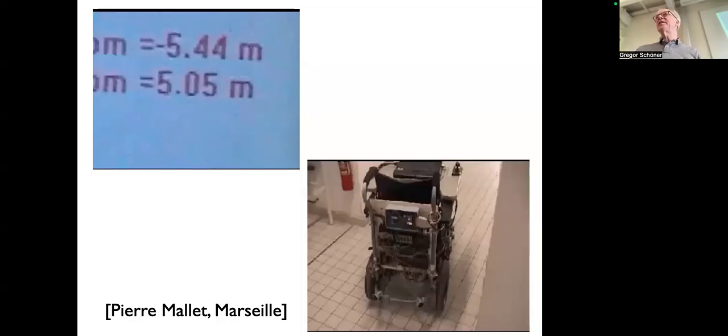In other cases, it is the sensors. The sensors need some time to set up this infrared. There's the flight time, but that's negligible. But they need to average a little bit. It's like heat, it's infrared, and the sensor has some time it needs to make a measurement, and you have to do that separately for every sensor because they interfere. And that gives you the minimum time for one time step. We get one reading from every sensor. We even did things like, at every cycle, only using 3 of the sensors and then the other 3 for the next time step and so on. And that limits the time scale of the numerical integration, and that determines how fast you can go. And so this is about how fast we can go.